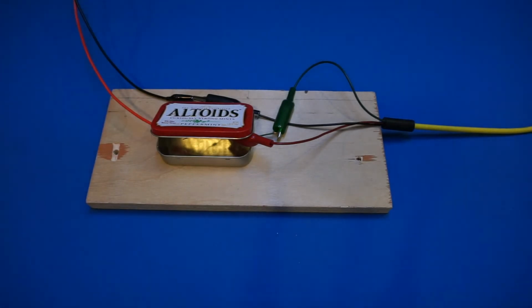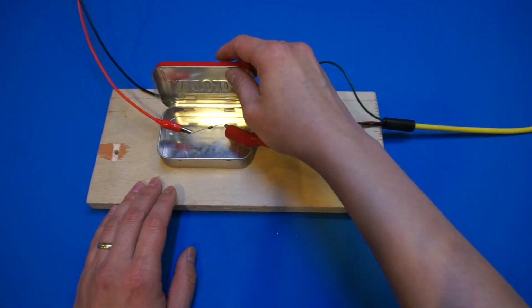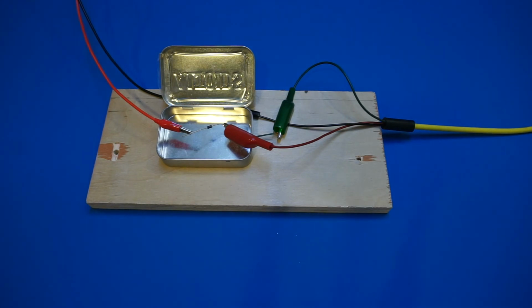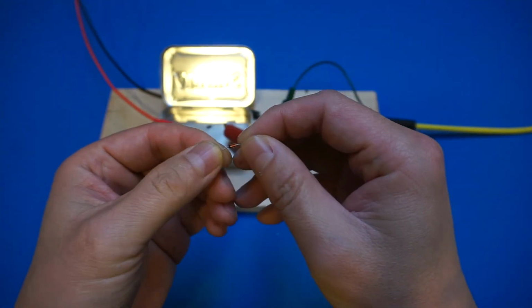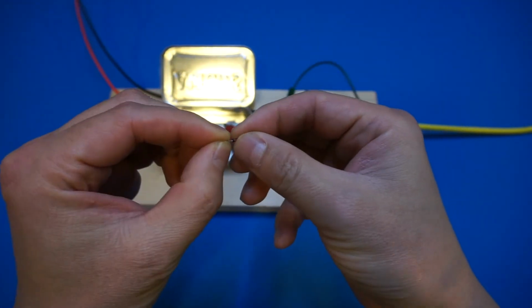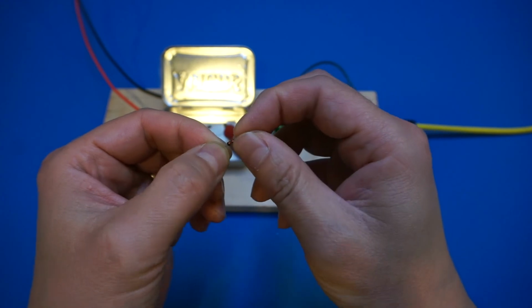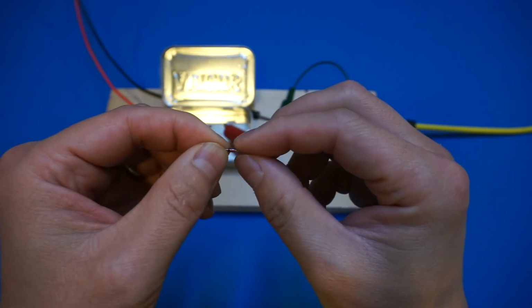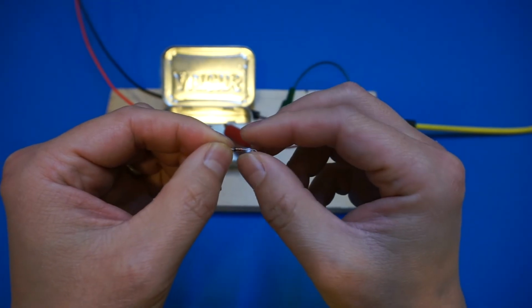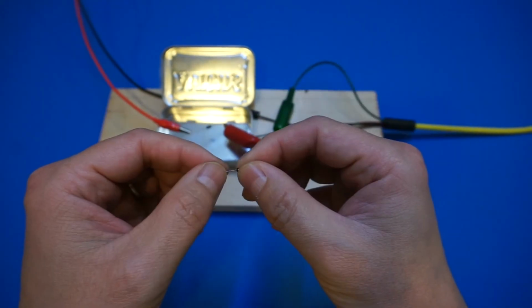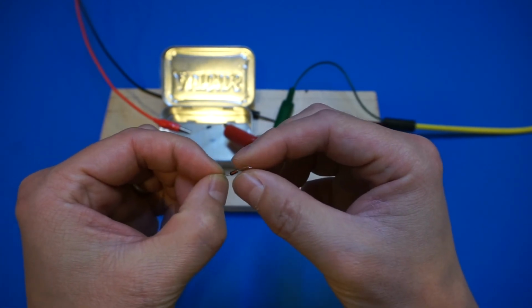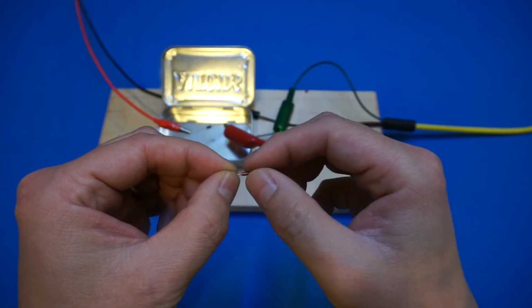And the diode I used here is a 1N4004, which is a standard rectifier diode. The reason I didn't use a signal diode like a 1N4148, for example, like this one, is because this has a glass casing. Typically the glass casing doesn't really matter, but in this case it does, because the glass casing can allow light to come through, and the minute photovoltaic effect can actually be measured, so it will skew the result.